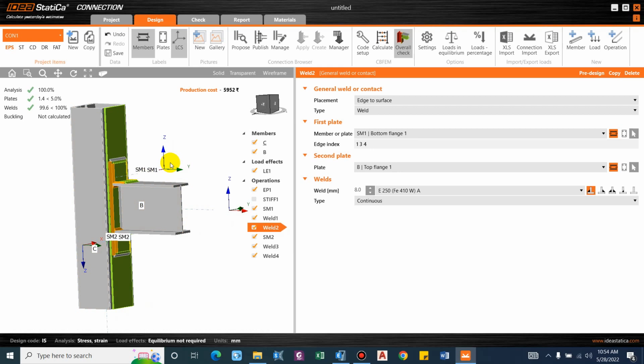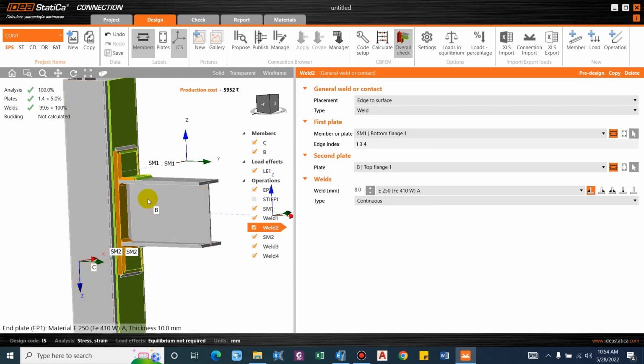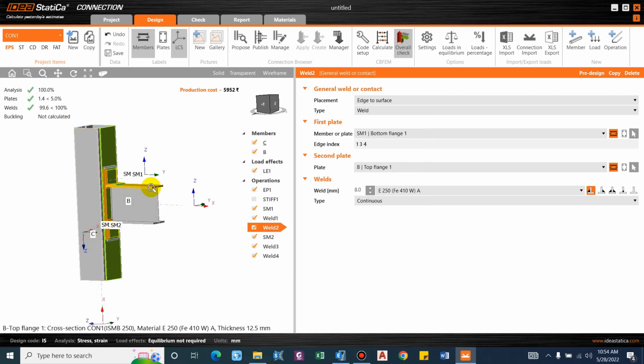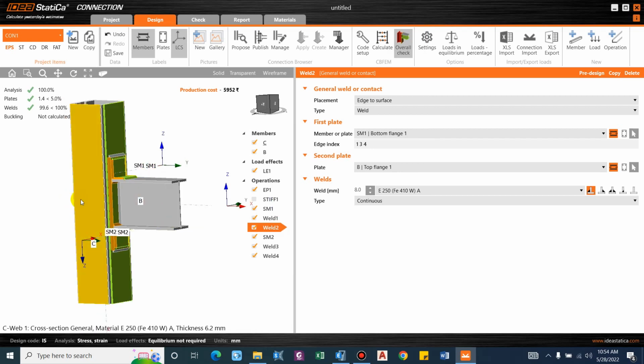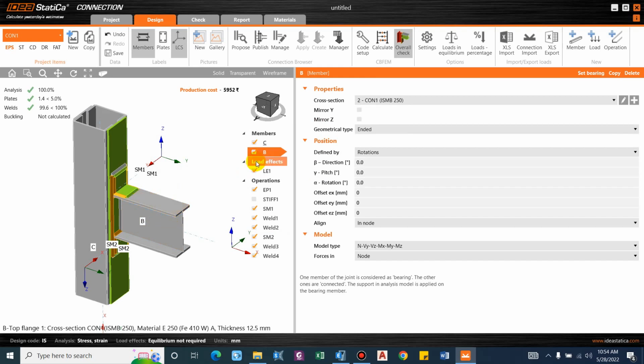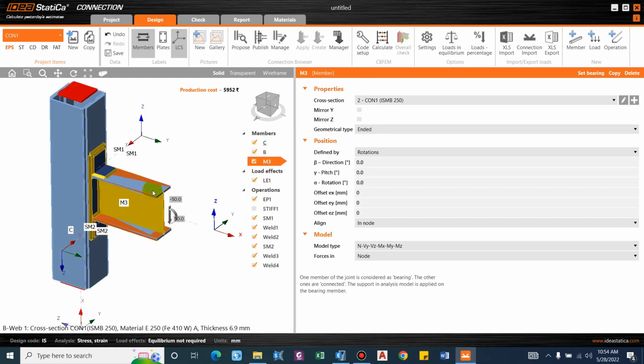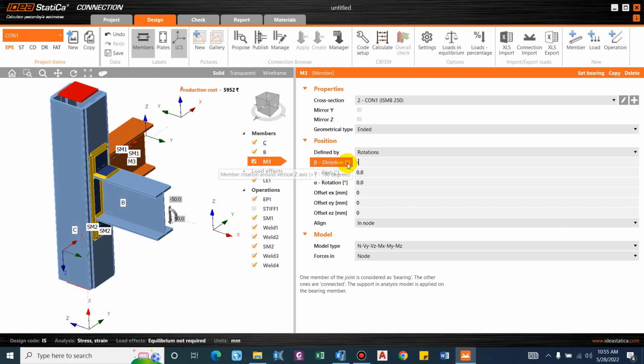We can also propose other types of stiffening members such as triangular stiffening members, but for now I have used angle. So this is one of the connection types. We also had a column in this face, and we also had a beam in this face. So you can simply add a copy of this and consider the direction as 90 or even minus 90.